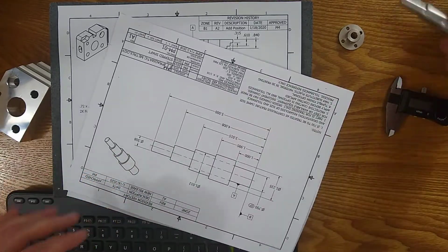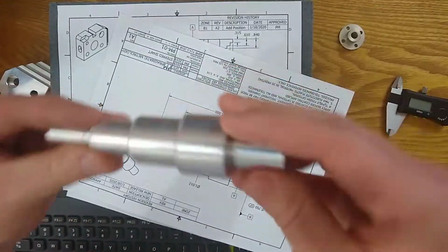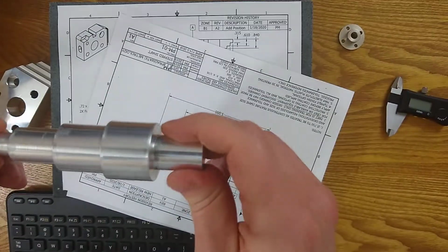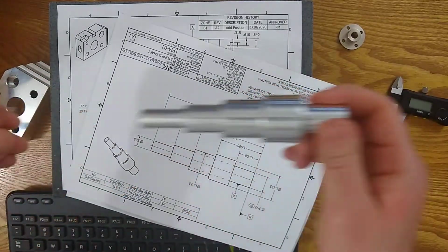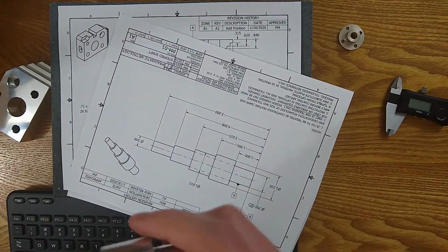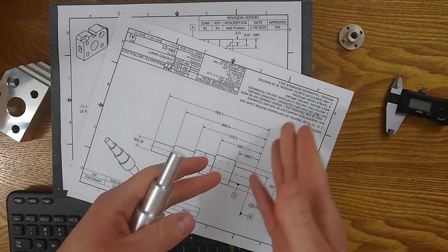A lot of people take for granted and assume all these diameters are on the same center line, but when you transfer parts, or make them with the mill, or do it in a way that people aren't expecting, it happens where they're not on the same center line, and problems can happen. I'll talk about how to verify that when we do the surface plate stuff, but just remember there is an implied relationship, and you're going to need to verify it, even though it's nothing you can point to.